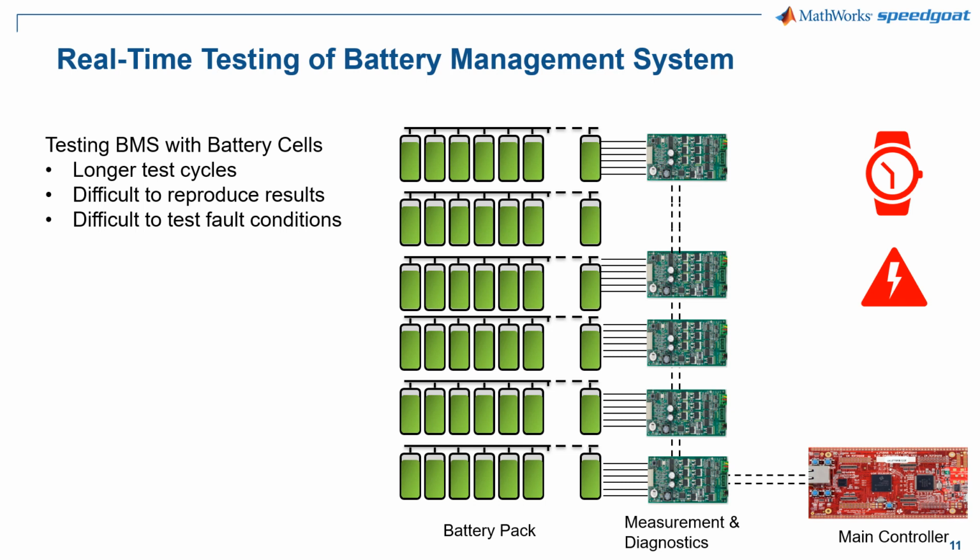While doing testing with actual cells, achieving test automation, test sequencing, and report generation can be very expensive and requires a lot of resources, especially when there are many test equipment involved. Doing extensive testing with actual battery pack is required for final system integration test and functional test. But it does not make sense to do this type of testing for every software revision or design iteration.